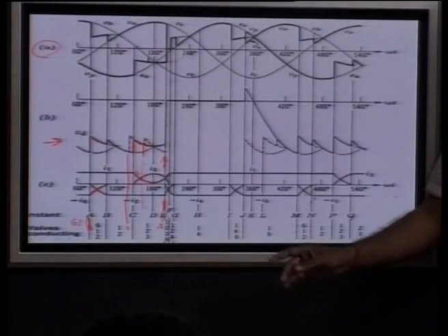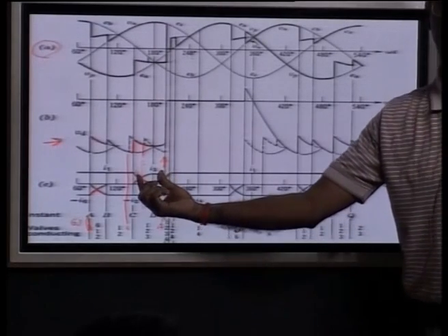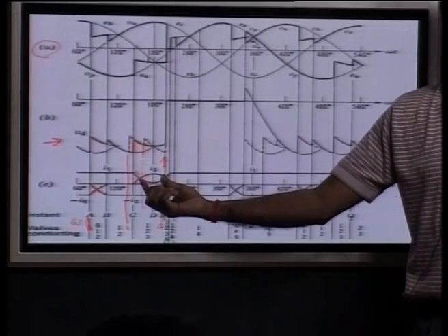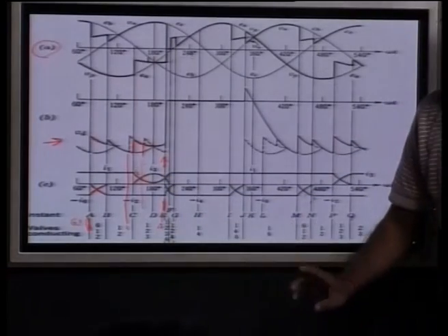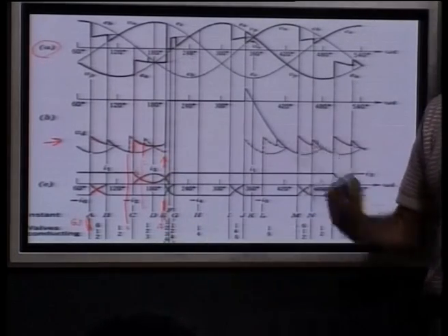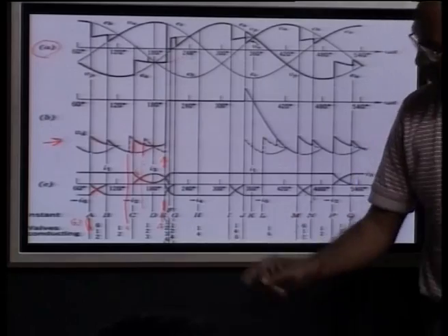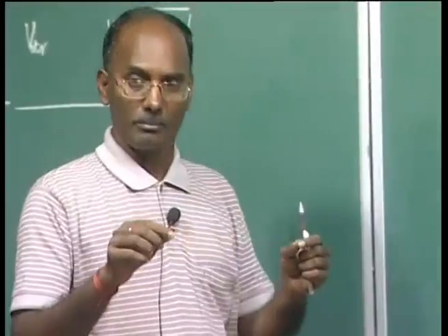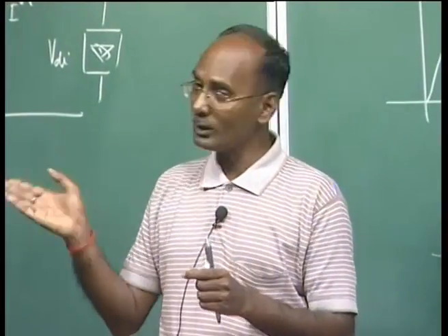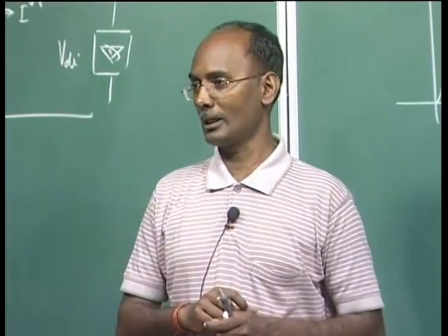Are you getting my point? Here what I want to tell is that this period is very large, this period can be lesser as well depending upon the circuit condition. So in this figure it shows that this is exceeding even the firing instant of 4. So 4 will be getting the pulse in the sequence order, 60 degrees. So at this E you can say 1, 2 and 3 were conducting because the commutation between 1 and 3 was still continuing, and 2 was earlier conducting and now 4 got the pulse.